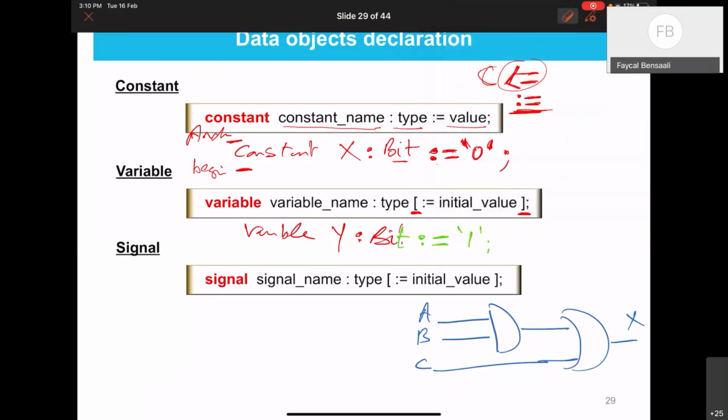So if you want to work with signals, do you see this line? Anything that is not a port, so those are ports, those will go into the entity, right? Anything that is used to connect two components inside your circuit can be a signal. So this one, I can name it S, for example. In my code, I can declare a signal.